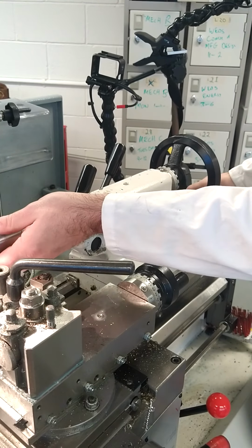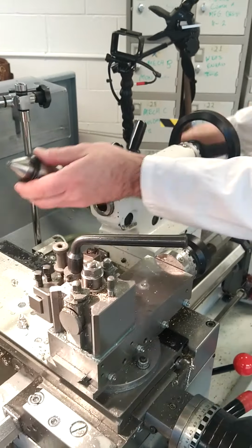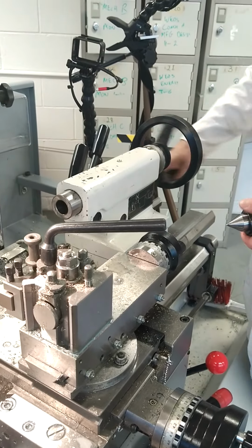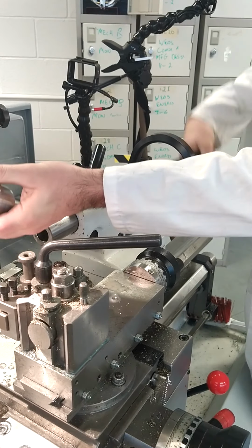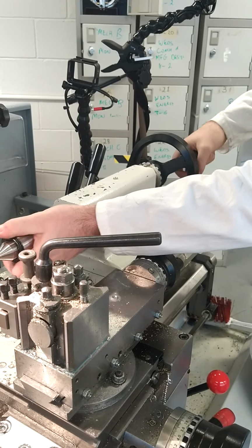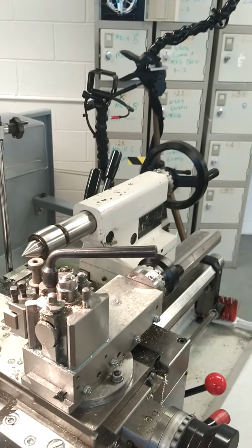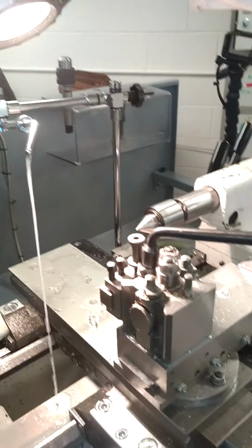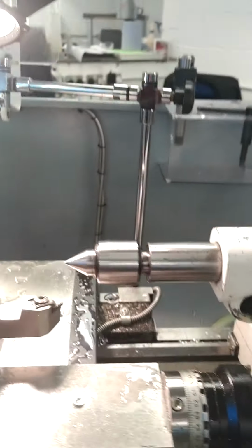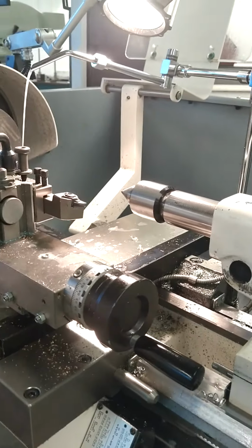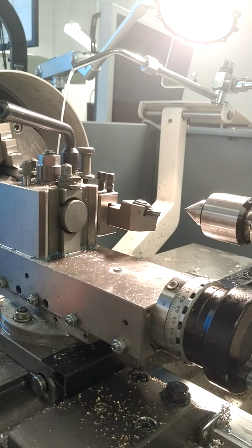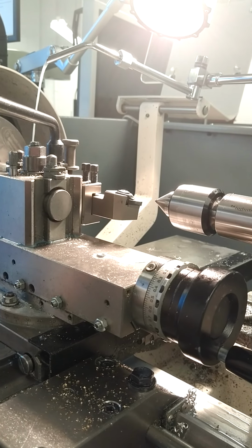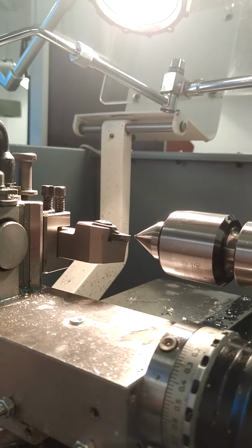To put it in, you have to ensure that it's wound forward in order to install, and the distance you have to move is about 56 millimeters. So now we're going to set the tool height. This is a vital step at the very start. Every single tool that goes into the machine needs to have its tool height checked on center. This will ensure you get a good surface finish on your part.